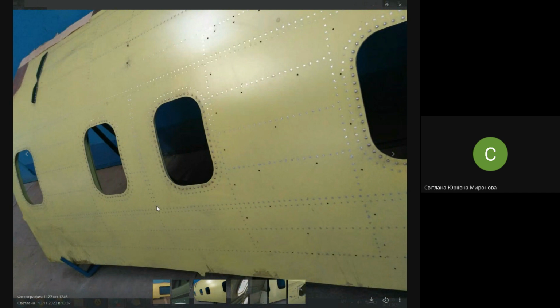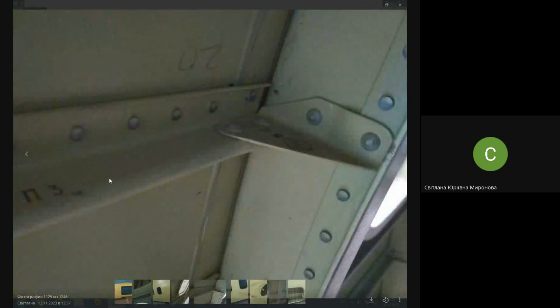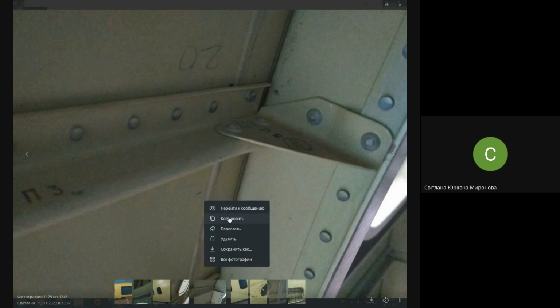Do you see? Somewhere you have a regular place. Here, there are so-called regular places. And somewhere you have an irregular place. Look, a double line of stringers. Why? Because here you have a reinforced stringer. Not that one, that is a simple one. No, reinforced is here at the under the window. Here its doubling plate is visible for me, along this line.